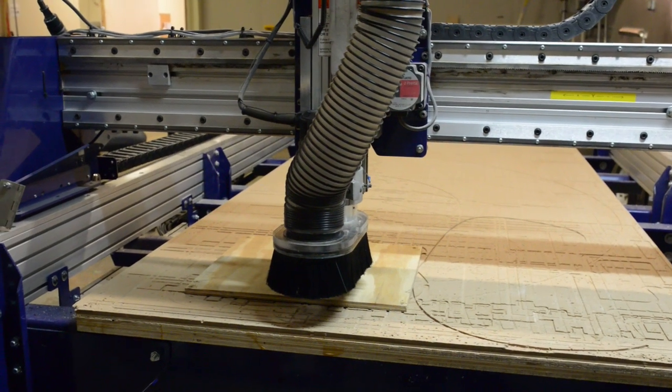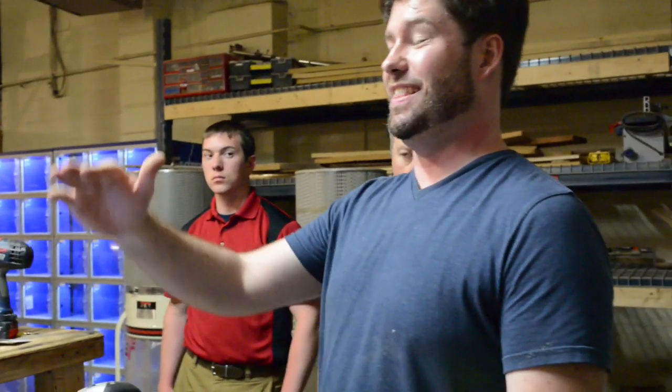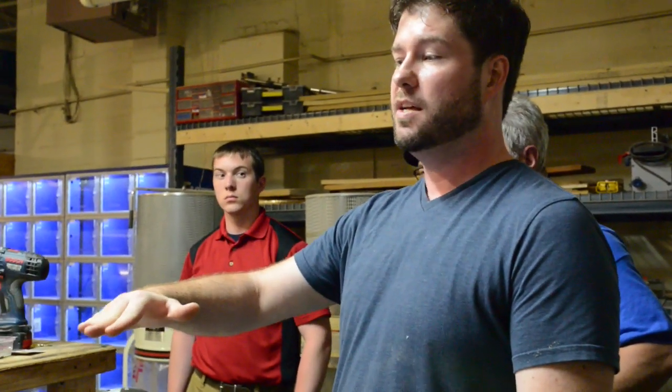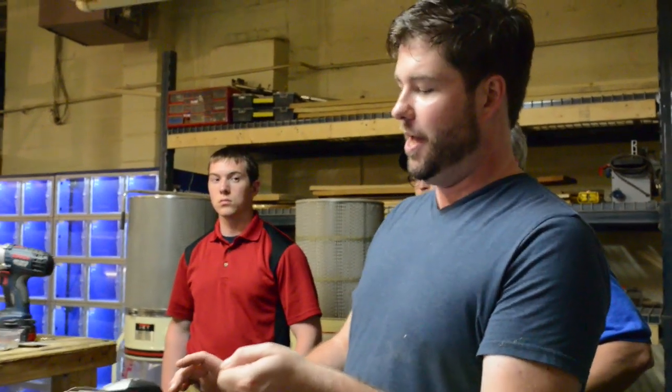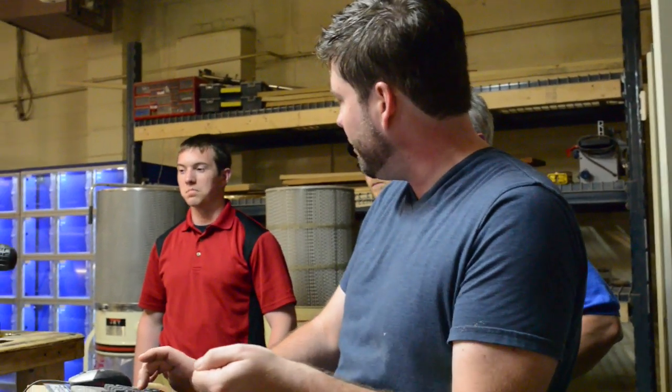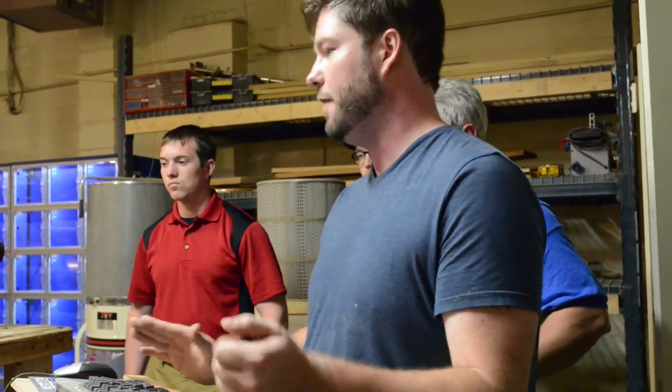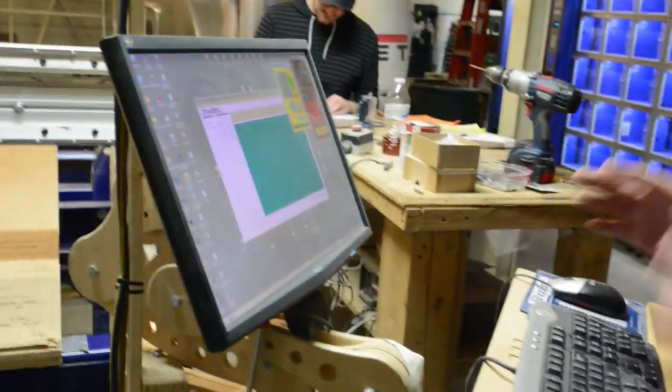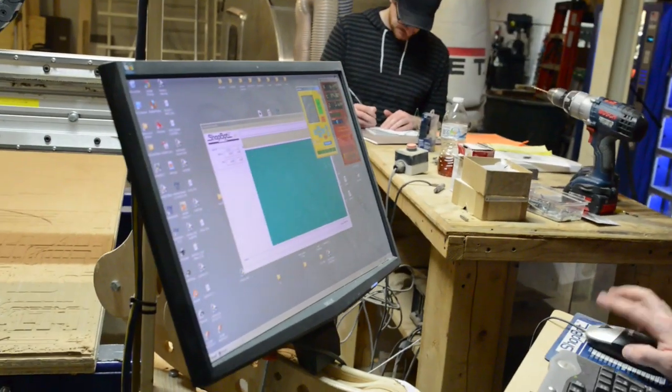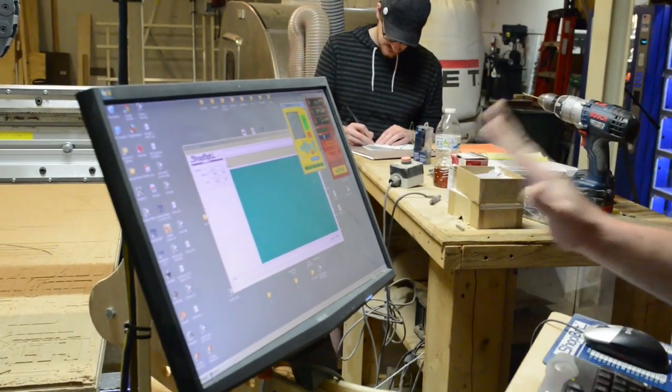When you get out, now there's a really special program. There's a program that does this, zeroing the Z, really well, very accurately, on the fly. Back in the day, you would have to get a dollar bill out or a piece of paper out and slowly lower the head until you couldn't move that piece of paper anymore. And then you would know, okay, that's close enough. Now you don't have to do that. There's a tool or a little program that does it for you. You have to get out of the manual control before you do this.